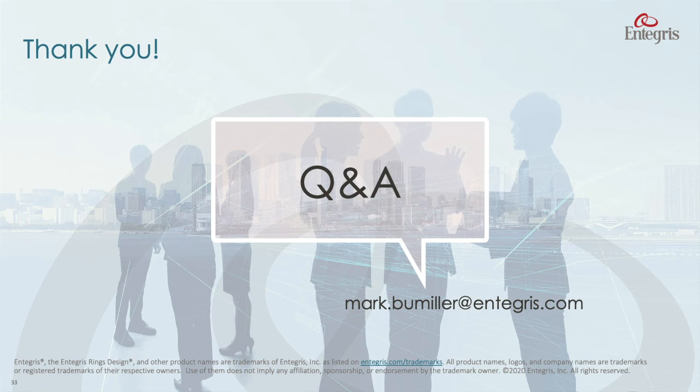Oh yeah. That's good. The next question I have is, how often do I need to recalibrate the instrument? Can I check the calibration myself? I usually would say this is a risk-based assessment. If your entire plant runs on, does my sample pass today, I'd be checking that calibration daily.